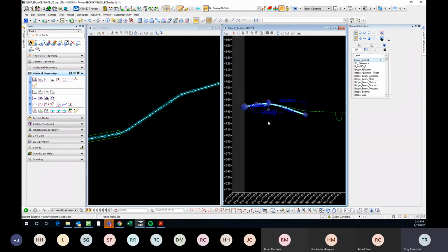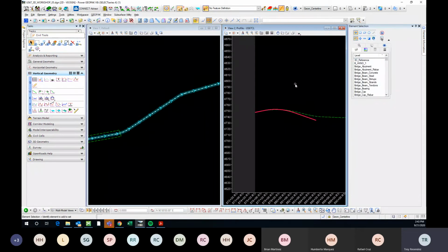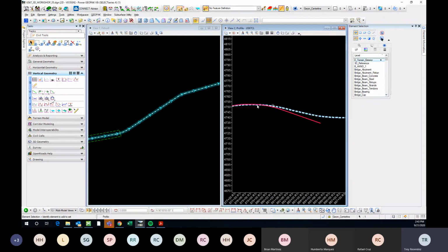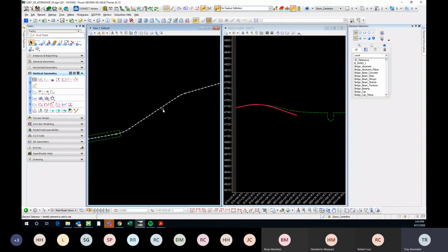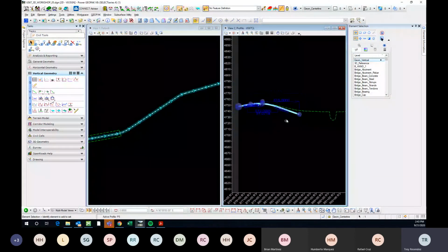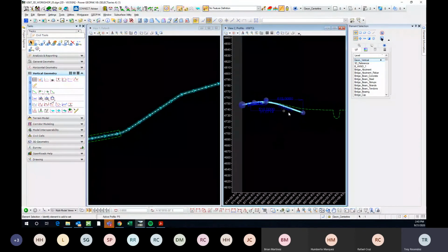And this is what we need to do, because this is how the template will know which geometry to follow. Because you could technically have it match existing as long as this existing ground is set active. So now if I come here and hover, we can see that our active profile is this P5 complex that I just chose.